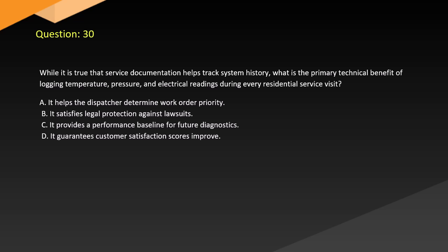Question 30. While it is true that service documentation helps track system history, what is the primary technical benefit of logging temperature, pressure, and electrical readings during every residential service visit? A. It helps the dispatcher determine work order priority. B. It satisfies legal protection against lawsuits. C. It provides a performance baseline for future diagnostics. D. It guarantees customer satisfaction scores improve.